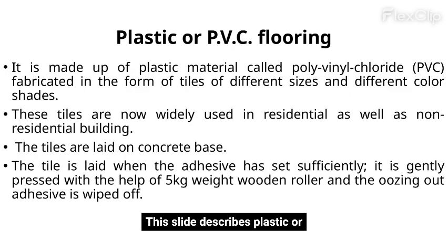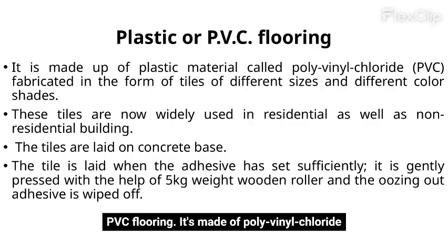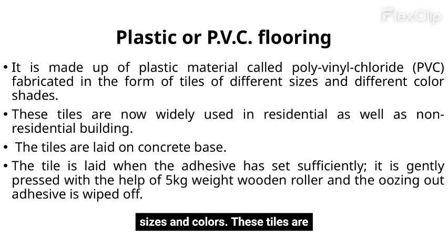This slide describes plastic or PVC flooring. It's made of polyvinyl chloride, PVC, fabricated as tiles of different sizes and colors. These tiles are now widely used in residential and non-residential buildings. The tiles are laid on a concrete base and pressed with a roller after the adhesive sets.